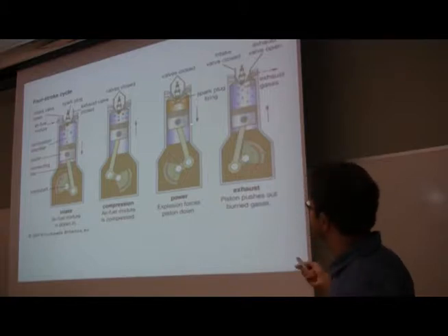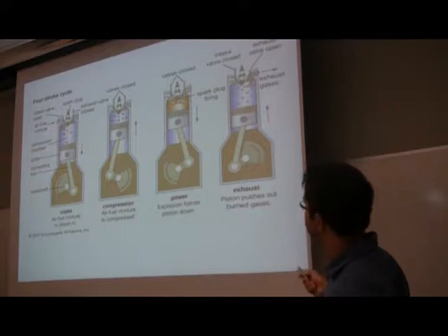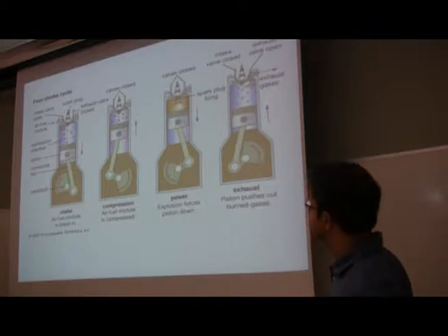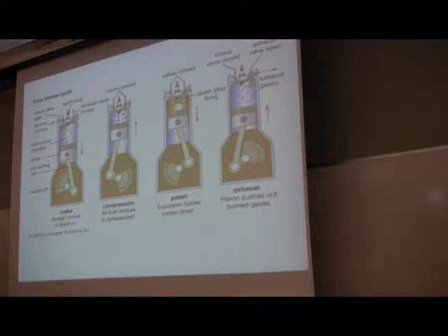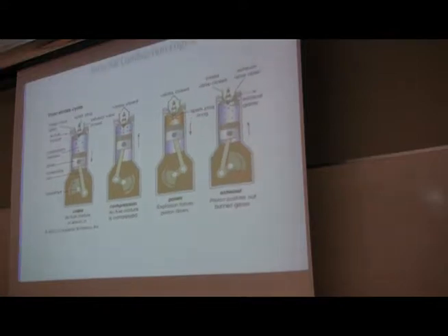And then you have a spark plug, which ignites an explosion. Because of the energy released as the gases expand, because they heat up, that pushes the piston down. And as it turns back out, you have exhaust. It pushes the burn gas out. Very simple. It's the most common, not necessarily the simplest, form of heat engine.